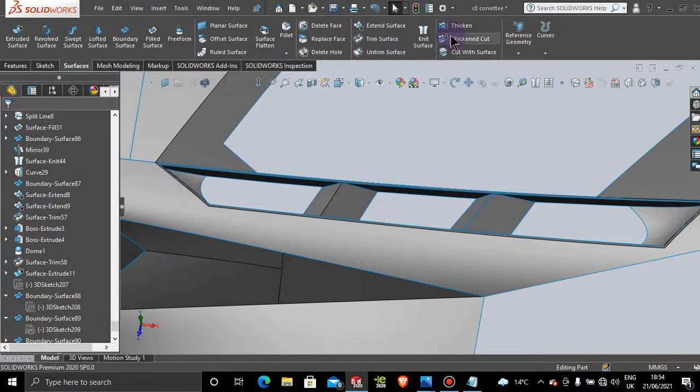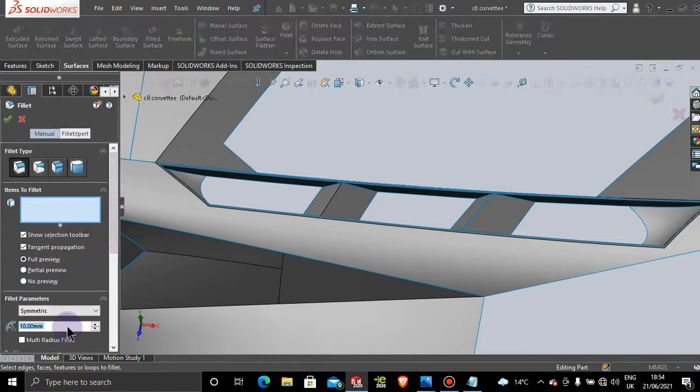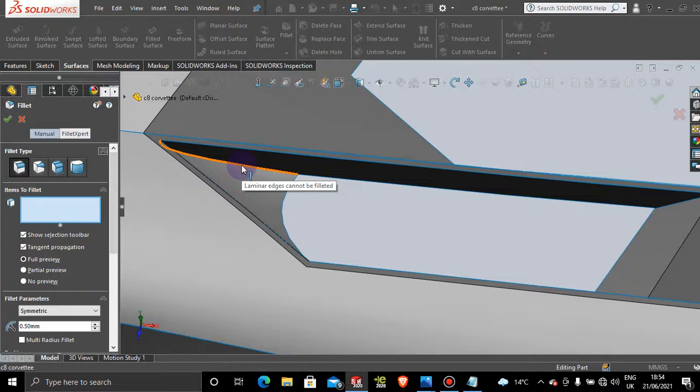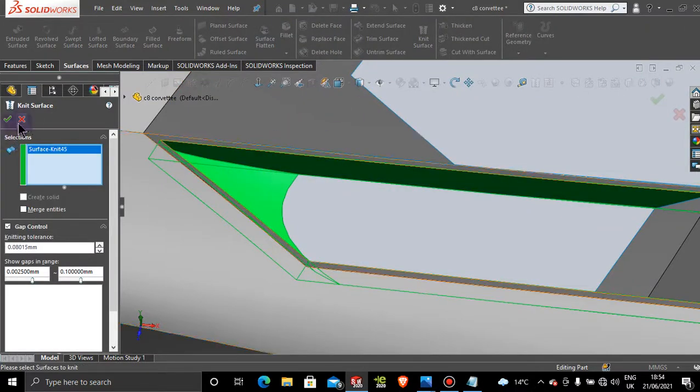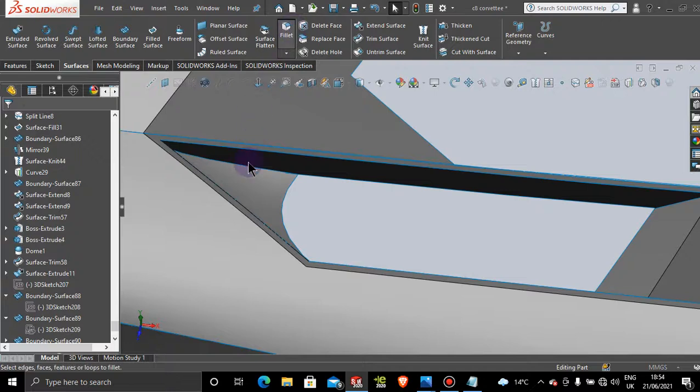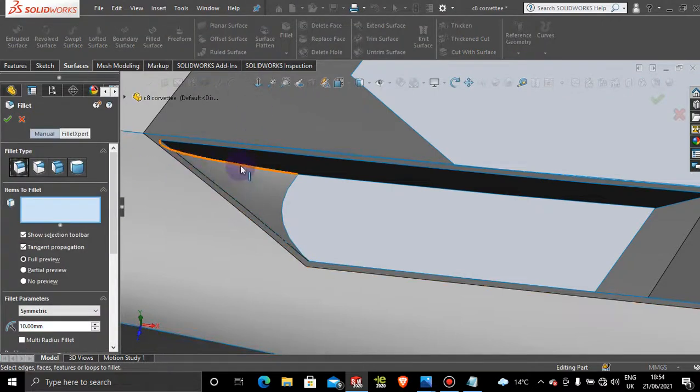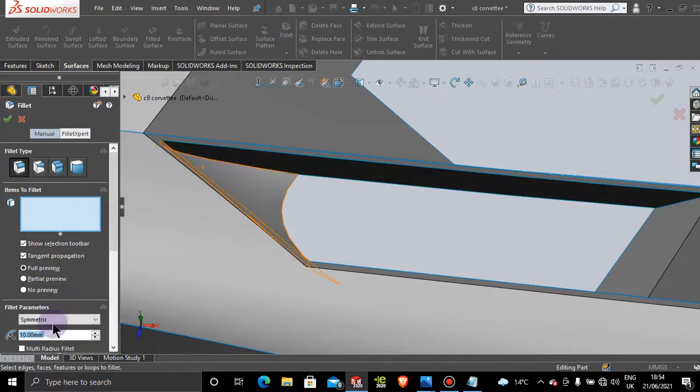All right, so let's try and add our fillet here. Let's try 0.5, 0.5, and see what that gives us in this small corner here. Did we not knit that together? So bracket and this one it is knit together. Let's see. I want to fillet this. Let's try 1 here, not 21. Let's try this corner here.